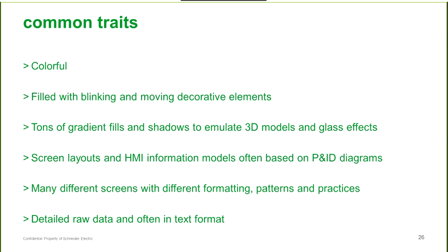Well, first of all, they're very colorful. There are big symbols on the display that don't give much information to the operator. There are a lot of animations. We're using a lot of 3D models and glass effects. The screen layouts are often based on the process and instrumentation diagrams. We have many different formats, patterns, and practices. We also present data as text, raw data, without any context.